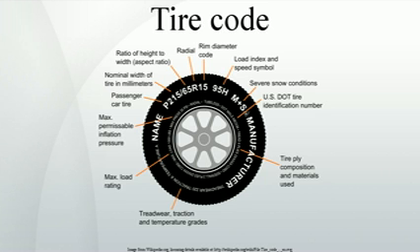Hence when the height is expressed as a percentage of the width, it is almost always less than 100%, and certainly less than 200%. Conversely, vehicle tire diameters are always larger than 200 mm. Therefore, if the second number is more than 200, then it is almost certain the Japanese notation is being used. If it is less than 200, then the US/European notation is being used.